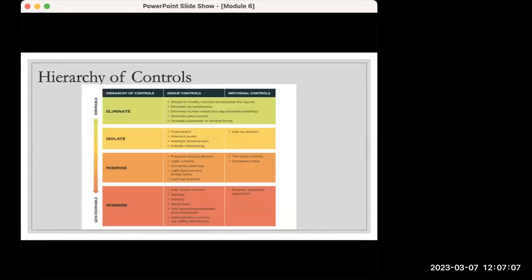Guards are the first choice of control to keep workers from coming into contact with hazardous moving parts or to contain harmful fluids and projectiles, particularly when access is not normally required during operation. Sometimes it is necessary to move a guard aside so a worker can access a point of operation during normal production work. If so, the guard should be interlocked to stop the machine and any hazardous movement of the equipment until the guard is put back in place and the safety control system is reset.